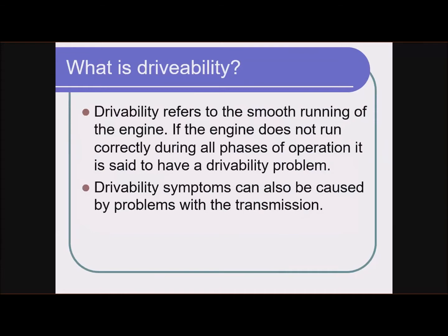Lack of power is definitely a drivability symptom, but the cause is not an engine performance problem, right? It's a drivability symptom, but it's not an engine performance problem. It's a transmission problem. So we see things like this sometimes. You could actually get a drivability symptom like lack of power from, think about it this way, a dragging brake, so a caliper is seized.